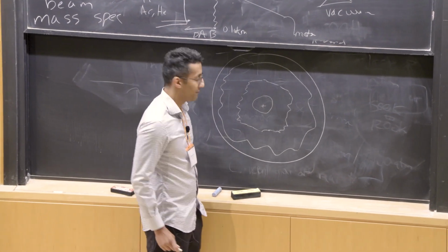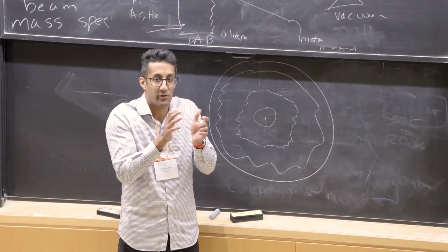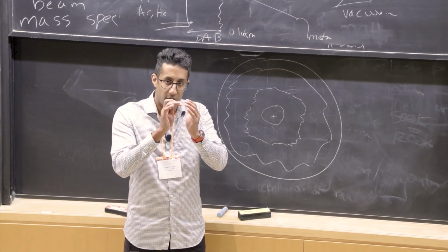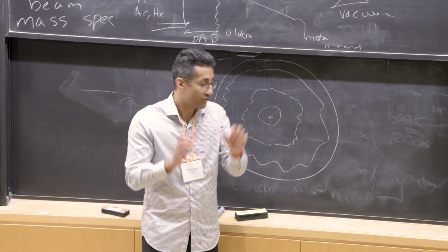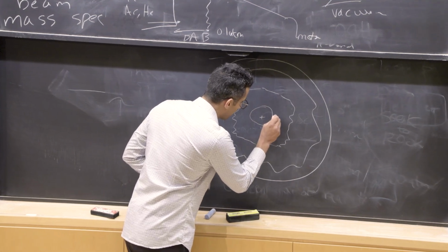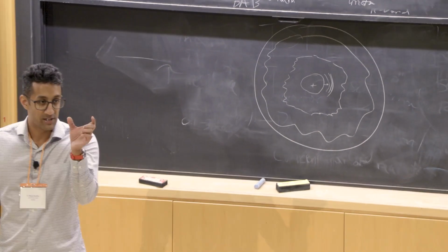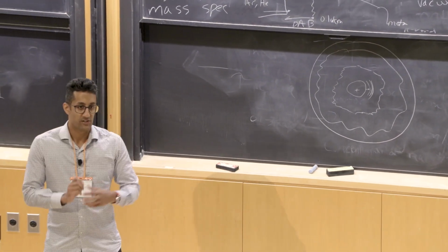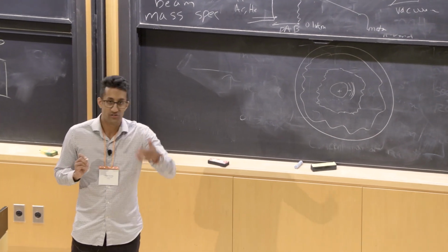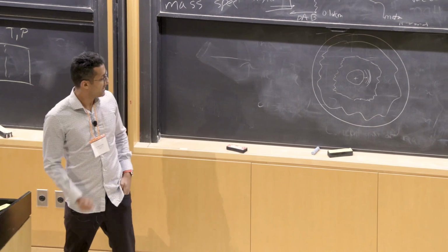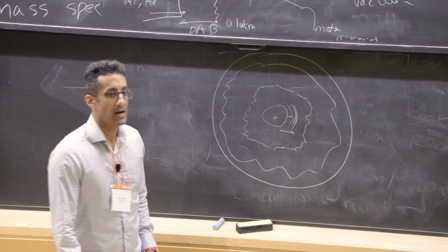Okay. And that round flame is usually not at the very beginning, because at the very beginning the spark creates a wrinkled flame structure. The flame starts growing. It's nice and smooth. And then they try to look with the camera. They try to track this flame surface as it grows. And it has to be done in only a specific period of the experiment. Because if the flame gets too large, then you get all these hydrodynamic instabilities. You can no longer track the flame front. And the flame speed is basically the propagation of this flame front as a function of time.